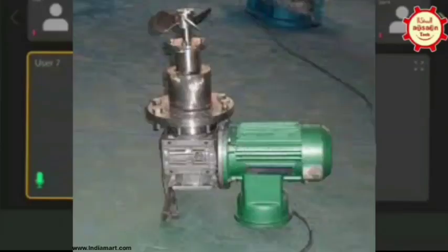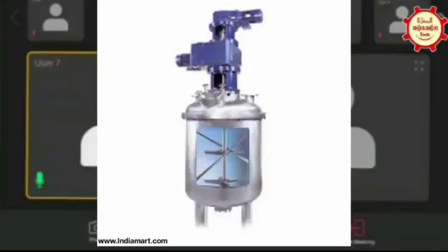We just want to confirm that because in a recent case there was a reactor, glass-lined, of 15.7 KL capacity, and in operation we faced the bottom anchor touching the bottom dish due to thermal expansion. Currently I am talking about the reactor which has only an 11 mm gap. It is in the design stage only, not yet fabricated. So we just want to make sure the gap provided is sufficient, at this stage only.